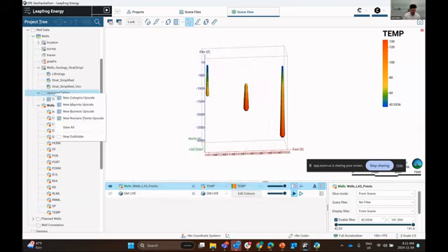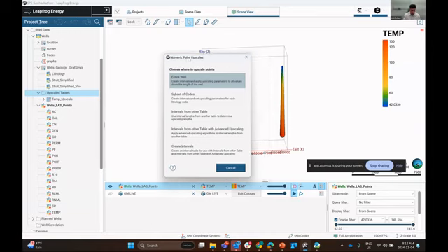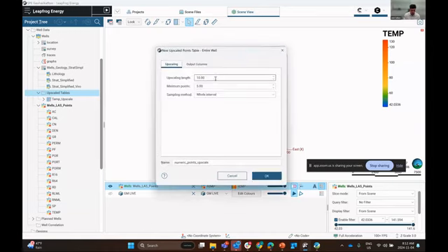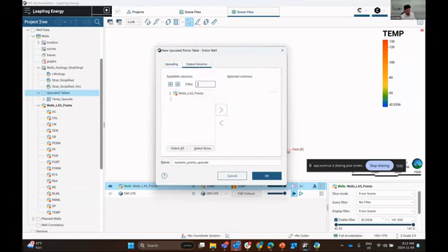And I'll just repeat that. Right-click, upscale tables, new numeric points upscale, and we'll go entire well. The upscaling length, again, this is a really quick demonstration, so I won't have time to cover all of the details associated with each parameter. But we'll go to output columns, expand out well last points, scroll down, and we'll choose the numeric value that we wanted to upscale.